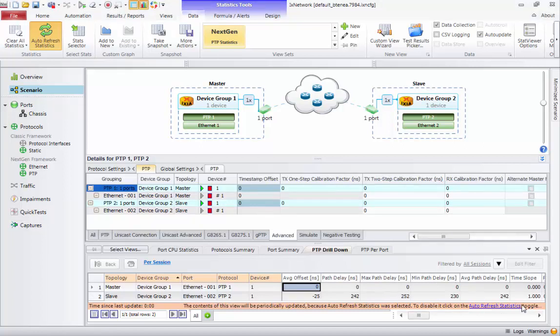Going now to testing actual timestamp quality. One of the most frequent problems with devices is that they do not actually include their internal PHY delays when transmitting the timestamps, and this can very easily be seen in the path delay. The path delay is the actual delay between the device we're emulating and the device under test, and considering that it's supposed to be around 4 or 5 nanoseconds for each meter of cable, right now we're seeing a pretty